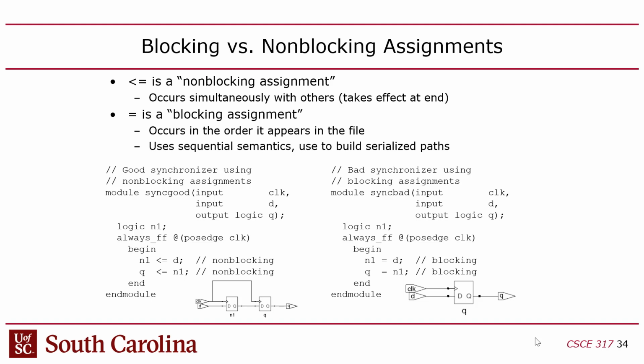So you can actually have multiple always statements. And as long as they're sensitive to the same instigating event, the clock, you can get confusion if you use blocking versus non-blocking in there. And I've actually had bugs in my code, and I think in some students' code too, that took me a really long time to figure out because we couldn't explain what we were seeing in the waveform window. It didn't make any sense. It wasn't acting the way it was supposed to, and it was because they had blocking and sequential logic, right?